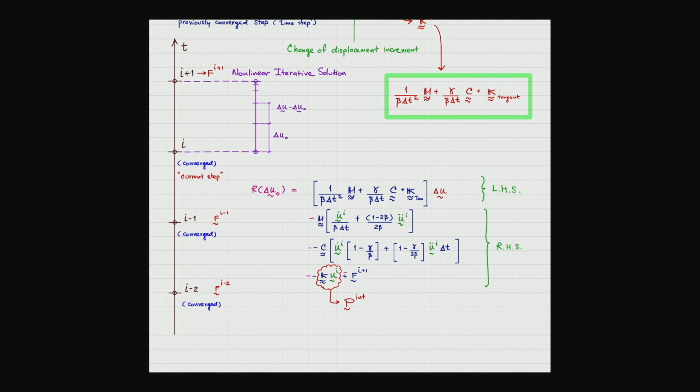Both implicit and explicit time integration are going to handle nonlinearities fine, but due to the nature of nonlinear problems, we want to discretize everything into the smallest size possible. So in the spatial domain, we discretize the x, y, and z, the physical domain, into small sizes in order to pick up the nonlinearities properly.